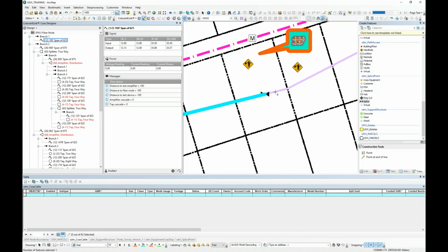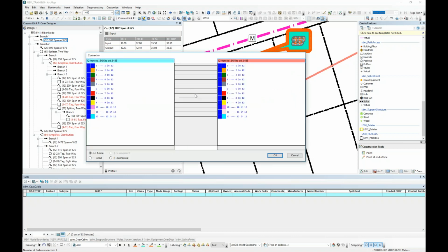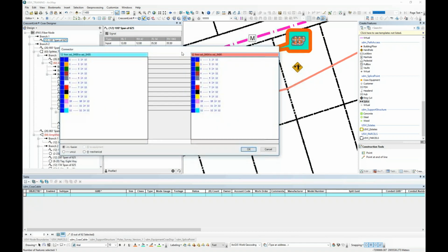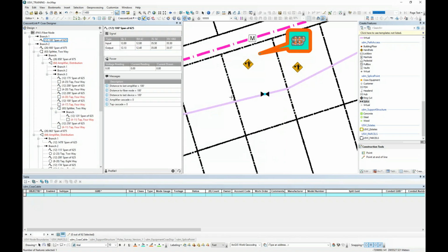Normally it still splices on its own, so it is uncut, because it'd be 12 on 12, so it just remains uncut, but you would see a loss in there if you have that calculated based on a splice point. It's smart enough to recognize that it's the same size on both sides. You're just putting a splice in, not pulling anything out.